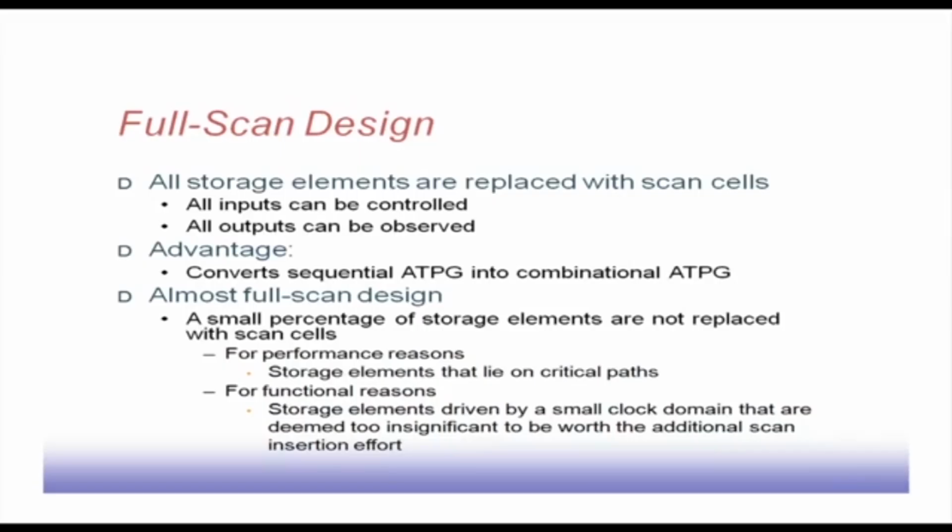If some flip flop is located haphazardly, far away from other flip flops, then when doing the scan stitching and making the scan cell, I have to have a long wire running from this cluster to that isolated flip flop to put it onto a chain. So, that also sometimes may be undesirable. So, that is the reason.